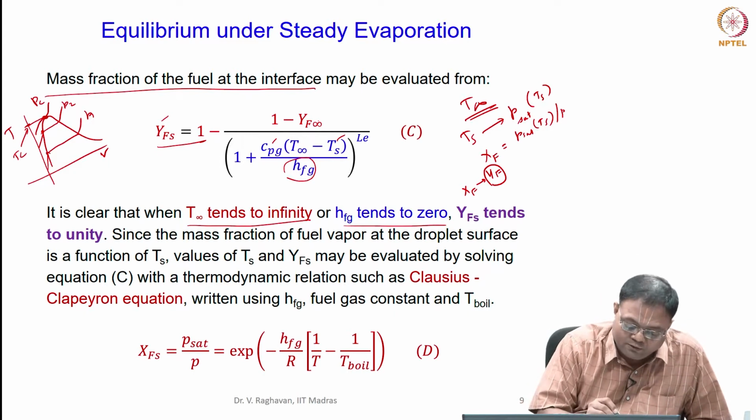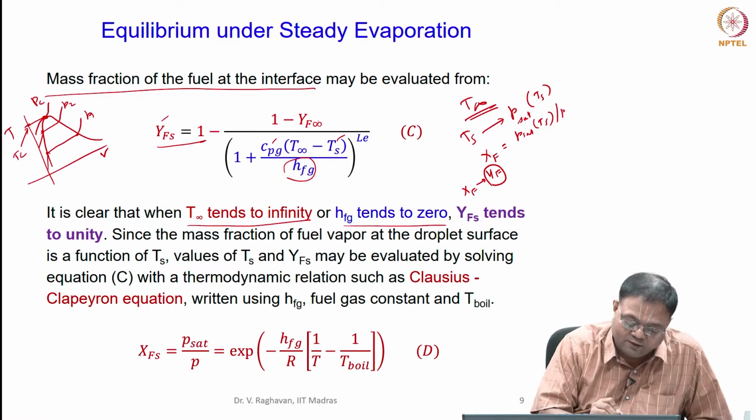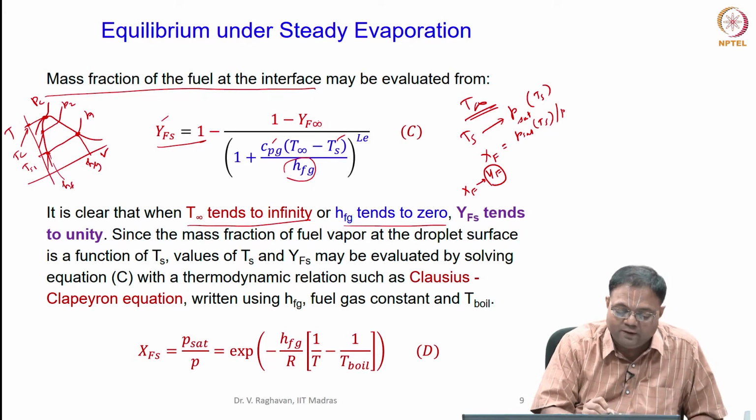Now, in these regimes where the pressures are lower than the critical pressure, there is a definite saturation temperature, say Tsat1, etc. Now, here, this is the vapor state, so this is Hg, and this is liquid, so this is Hf, and there is a difference.